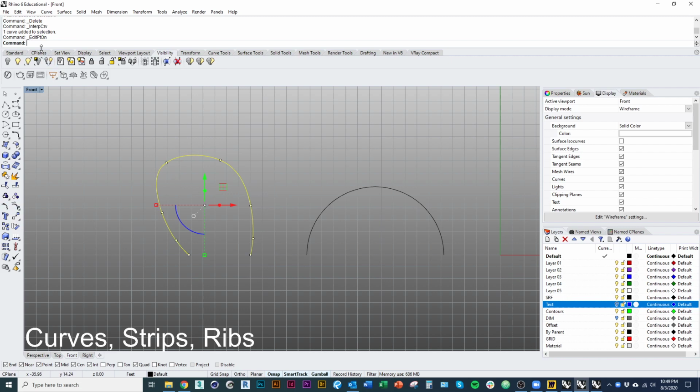And you can see when I click that, I now have the control points that are actually on the curve, and I can move them around. The same type of points that I used to originally draw the curve, I can edit the curve with. And by the way, you just hit escape to make those points go away, either type of point. Just hit escape on the keyboard.